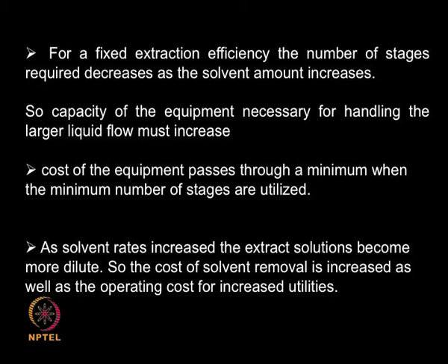But then if I am going to have a smaller number of stages and more solvent, obviously the size of the stage has to be sufficient for handling so much of the liquid. So, each of the stages may be of very big size. So, you see the advantage of reducing the number of stages is balanced by an increase in the size of the stage.